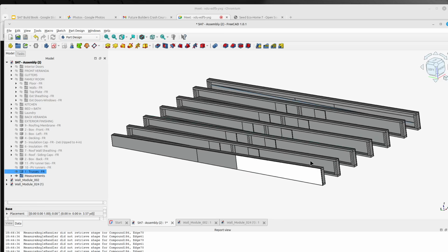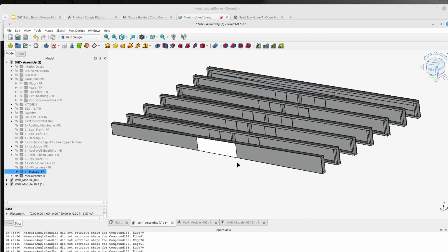But we really like these trusses. These ones are 20 feet and they have the slope built in, so you avoid any other mechanism that you need to put in for creating a slope on the roof. Therefore, the wall sections of all the walls are just a box, and you have these other components laying on top of that. Nothing like a riser or some kind of angling mechanism which allows you to get that drainage slope. So I'm just saying this is what we will build.